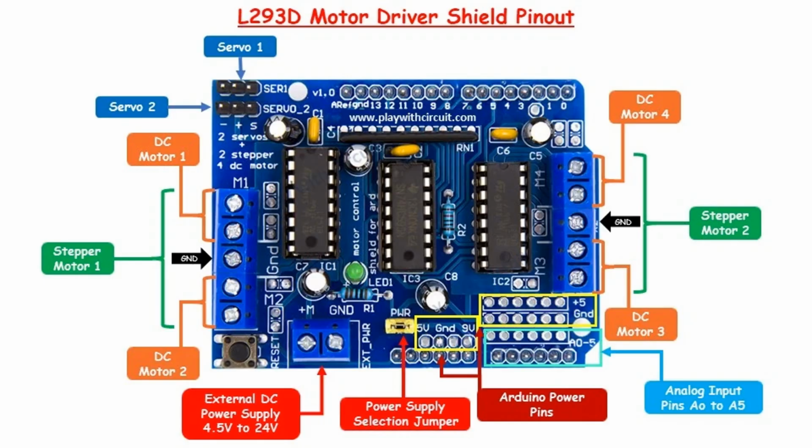Feedback from the encoder is used to detect discrepancies between the commanded position and the actual position, allowing the system to correct itself. Advantages: higher accuracy, better torque performance at high speeds, and the ability to maintain precise positioning even in dynamic environments. These drivers also help prevent stalling and overshooting, which can occur in open-loop systems. Applications: used in high-performance robotics, industrial automation, CNC machines, and applications requiring real-time adjustment to changes in load. Examples: Kollmorgen, Mitsubishi, and other industrial-grade servo systems with feedback control.